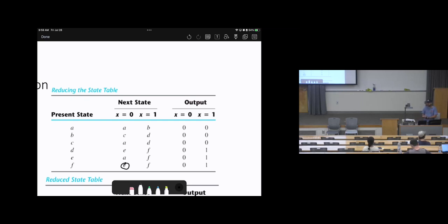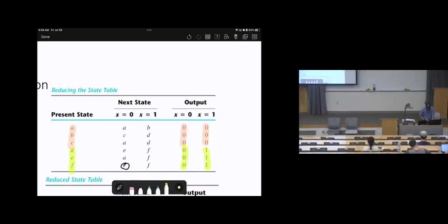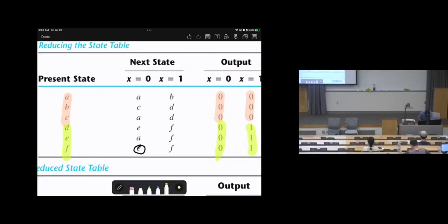After doing this simplification, don't stop. Check if there are any other possibilities that we can achieve. How? Let's make another observation. Look at the inputs and the outputs. Here is 0, zeros. Then we need to look at the other side, which is 0, ones. Let's look at state A. Can we merge A and B? I don't think so. A and C, no. B and C, no. Let's look at the other side, which is D, E, F. Those are F, this is E, this is E. So as a result, we can say D and E are equivalent.